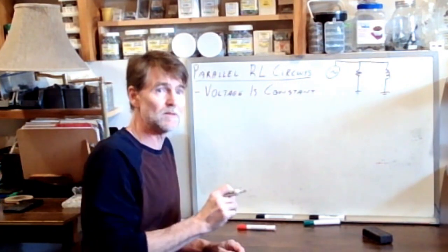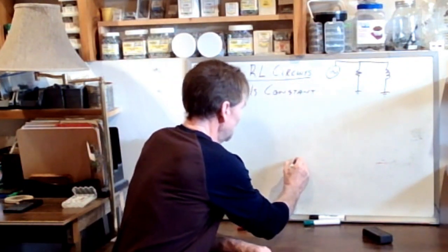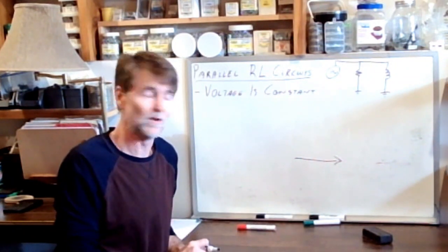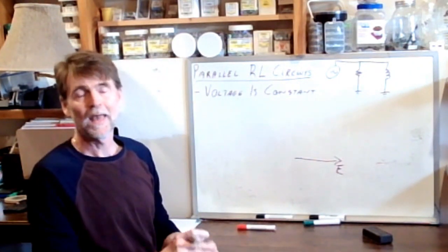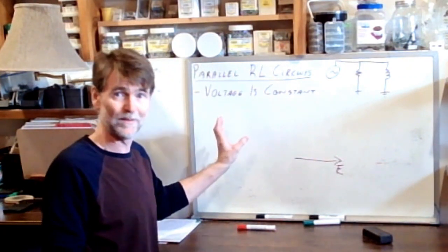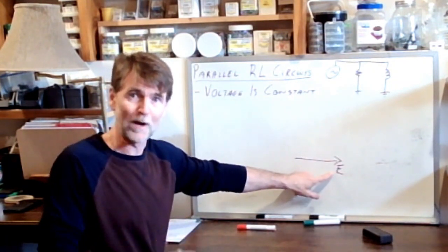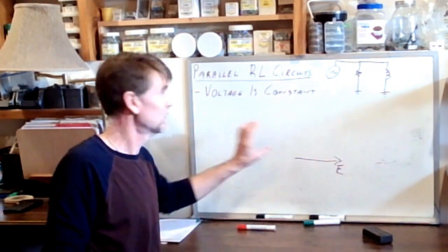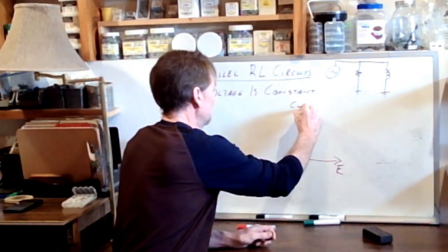That means now it's our voltage vector that we're going to place at 0 degrees. So instead of 3 current vectors at 0 degrees to build our 3 triangles, it's going to be 3 voltage vectors at 0 degrees. And in a series circuit, because the current was constant, our 3 triangles were impedance, voltage, and power. Now that voltage is our constant reference point at 0 degrees, our 3 triangles are going to be impedance, current, and power. So let's look at current here for a second.